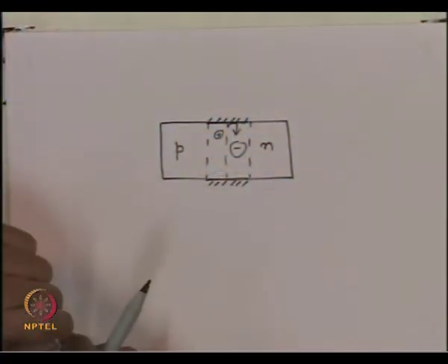The same thing is happening in this case also here inside the laser diode, that again the current is injected, and as the current increases, all the losses which are there inside this device, the stimulated gain takes over those losses and the photons are confined inside the region.